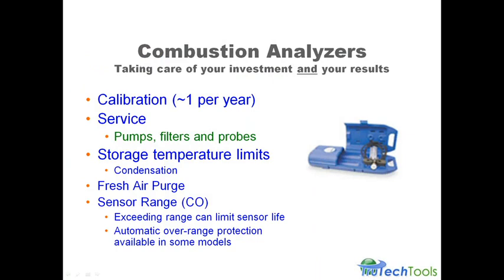So I don't want to expose my sensors to any more CO than they have been. I'm going to disconnect it. I'm going to take it outside. I'm going to leave the pump run for 10, 15, 20 minutes, an hour if I have to, till that CO gets back down to 0. Because we're flushing that cell.